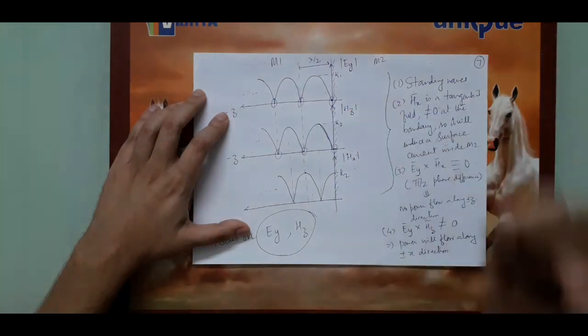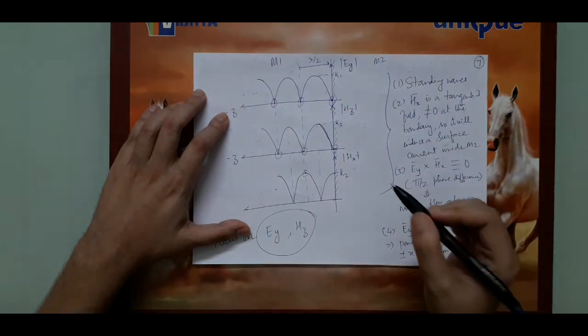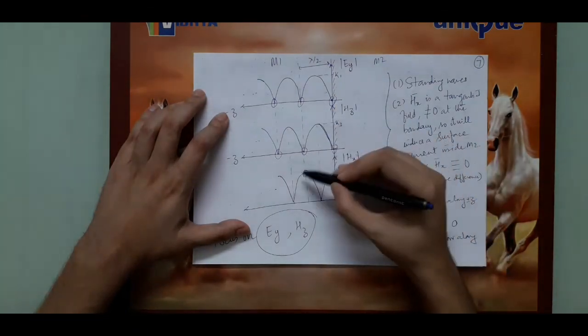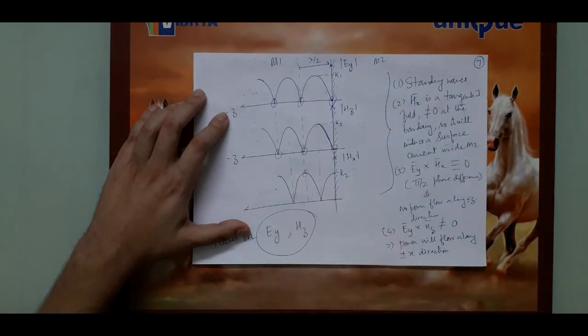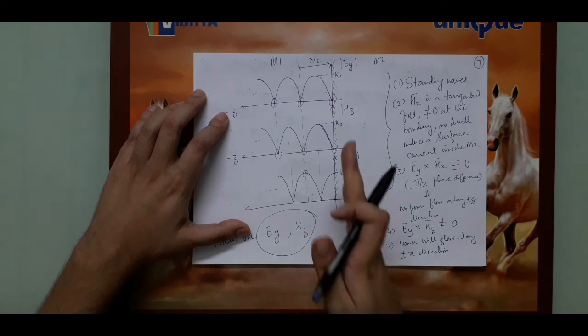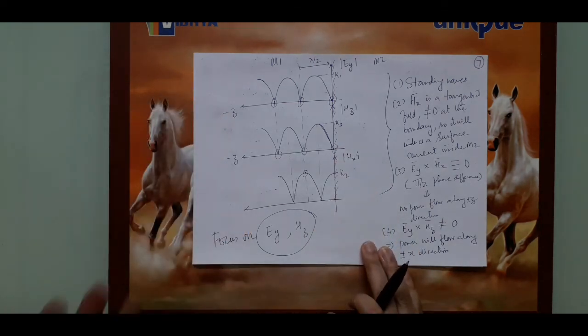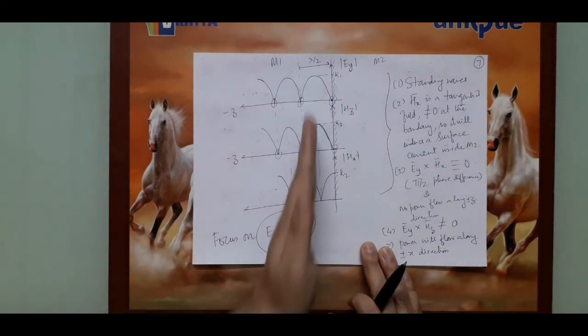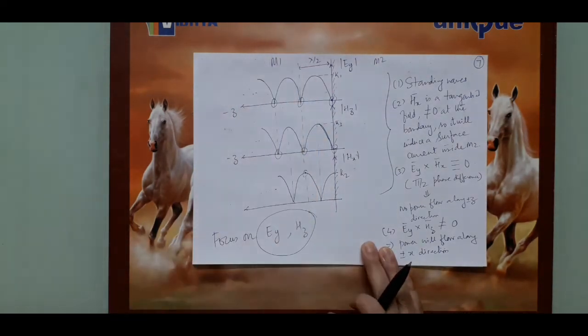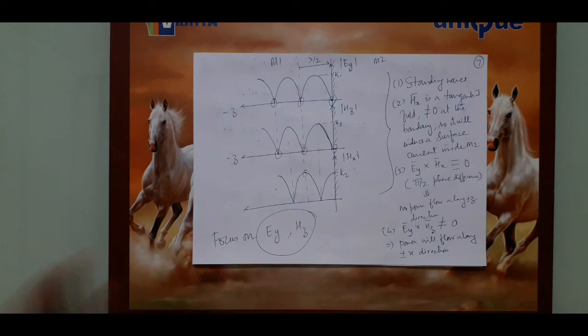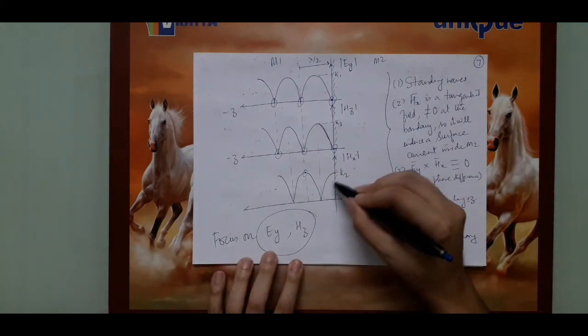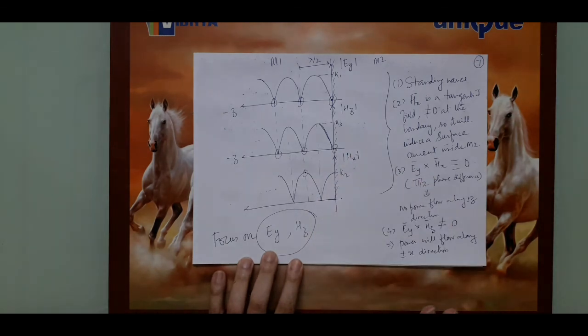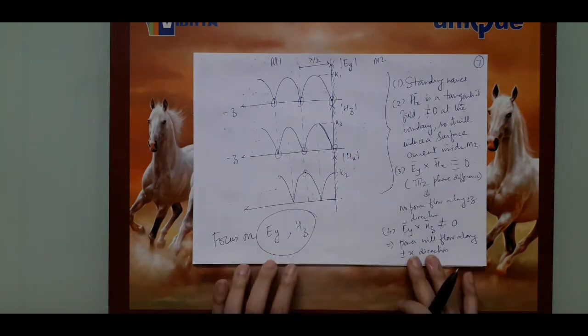Ey and Hz are becoming 0 and Hx is reaching a maximum, exactly the same as what is happening at z equal to 0. So it's like saying, if I place another conductor at this lambda by 2, it will make absolutely no difference. All I have to ensure is that the wave is hitting either of the conductors at angle theta I.